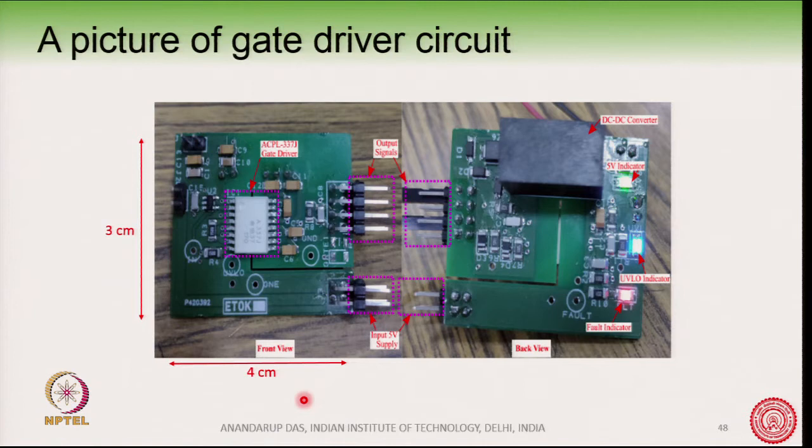Even this is not very optimum, you can make the gate driver board even smaller. This gate driver board has many protection features, as this driver IC also provides. It also has an isolated DC-DC converter, and there is also a cut on the PCB, so as to provide a physical isolation. We have been using this gate driver board to drive the SiC MOSFETs, but it can also be used for driving IGBTs or silicon MOSFET.